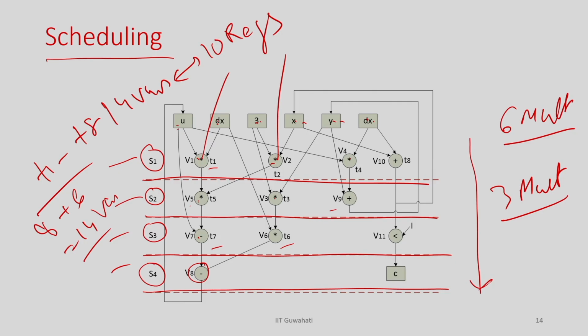So, that you have to do now, because that is how you actually realize the data path or the hardware. So far you just decide the clocks; after scheduling you only know you need 43 clocks to execute this behavior, nothing else. So now you have to realize, okay, I need 43 clocks, but what is the resource I need? The resource is basically two types: the data path, the function unit and the registers. Register to store the variable, function unit to execute the operations.